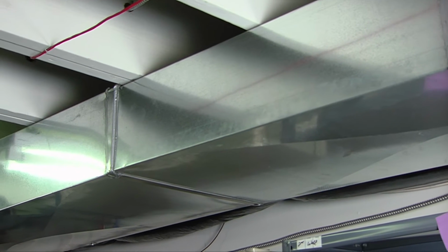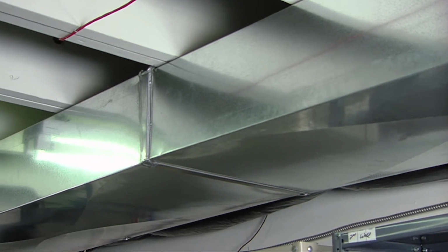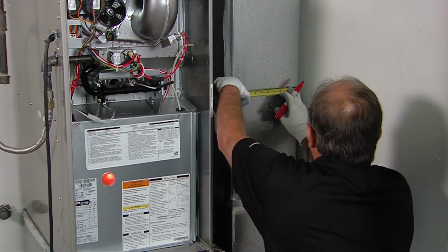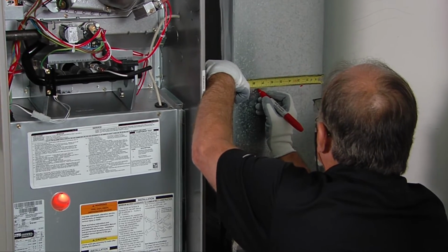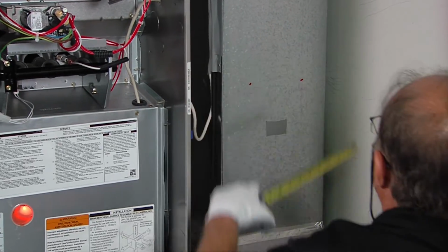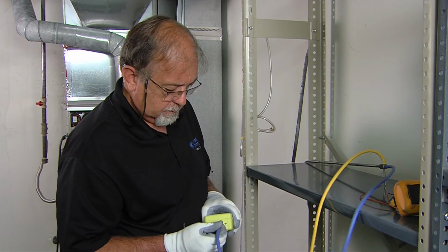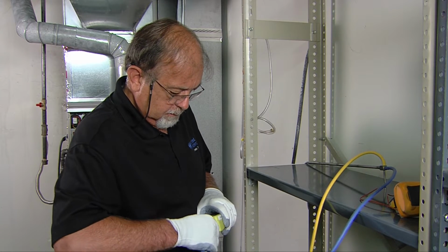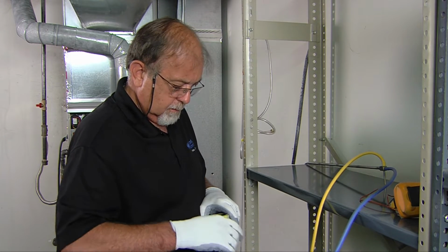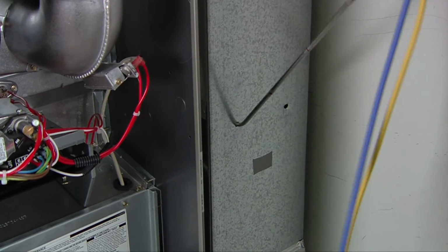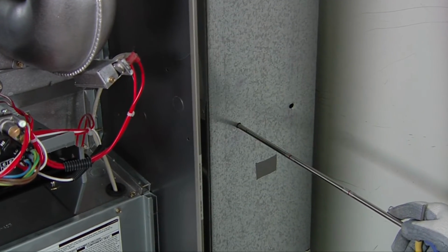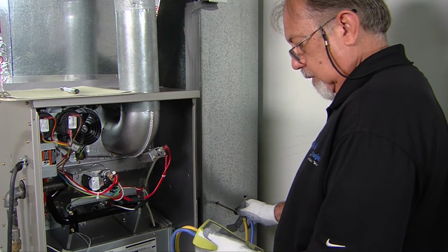You can measure airflow in a system several ways. This video will cover the technique of measuring the velocity pressure in a duct system. It is important to understand that the indoor furnace or fan coil equipment is an air-moving device. Fundamentally, the air entering the device will be the same amount of air leaving the device. This video is a simplification of one method shown in the service training program, Air Properties and Measurement, available from the Bryant Training Center.